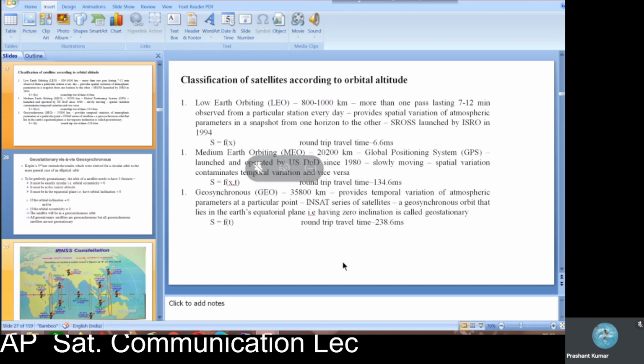Okay, that means while pointing the downlinking signal towards, say, a low Earth orbiting satellite or any kind of satellite, if there is an error of 1 millisecond, it means that your downlinking beam, the beam which you want to be received by your receiving base or your user base, will be off by 300 kilometer. So suppose instead of Kolkata, that beam will point, suppose 300 kilometer from Kolkata is maybe Baharampur or something, if we are going to the northeast.